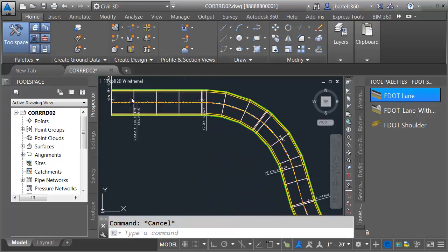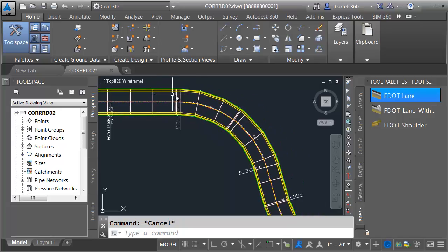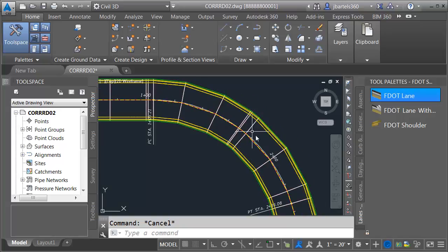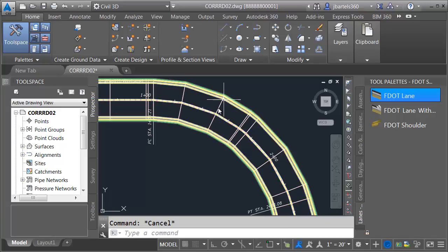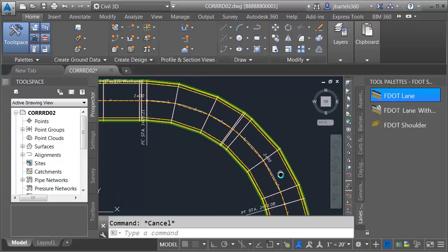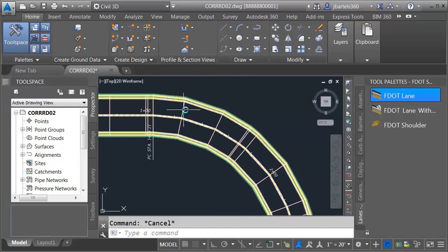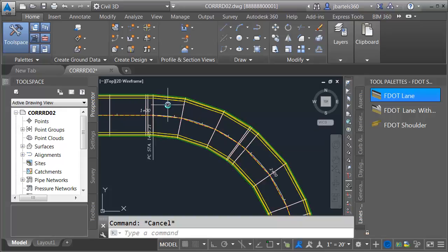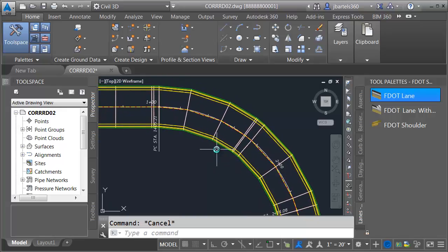As the assembly is copied along the design, you can see they're straight line connections. When we get into an area of a curve like this, you can see it doesn't look very round. We're restricted by how often the assembly has been inserted around the bend here. So this is called frequency. If I want to have a smoother arc here, I need to increase the frequency of the insertions of the assembly in the rounded areas. Let's look at how we can do that.